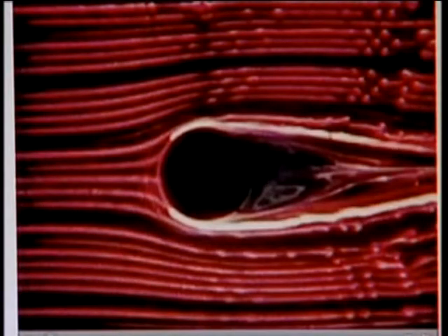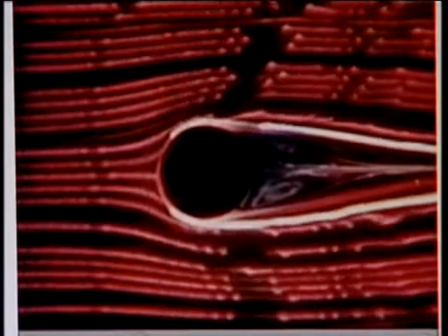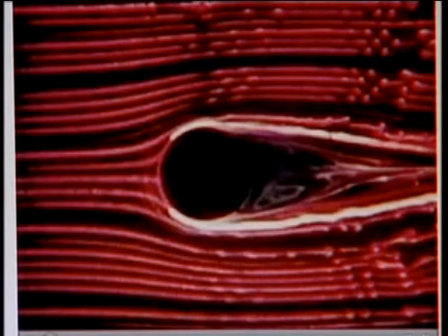These are made because of one reason, that laminar boundary layer is converted into turbulent boundary layer, so that it remains attached to the spherical surface. Because of that, the resistance offered by the ball gets reduced, and by virtue of that, with the same force, it can travel more distance.